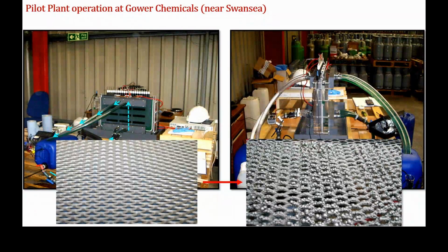And it also enhanced mass transport in the system. And you can see that by the end of the plating, the deposited nickel, this kind of morphology, is not very nice. It's all full of nodules and lumps and bumps, and that's because we pushed the process close to mass transport control. So there were lots of factors that make the deposit morphology not something that you would desire in a normal application, but for us it was okay, because it was just the recovery that was important. Ultimately the idea was that you can take this deposit and melt it down and reform it into whatever morphology you might like.